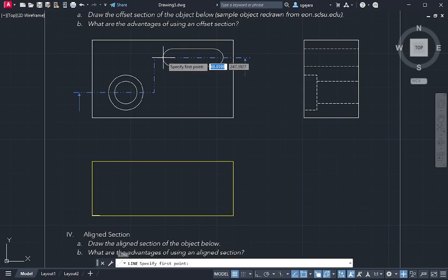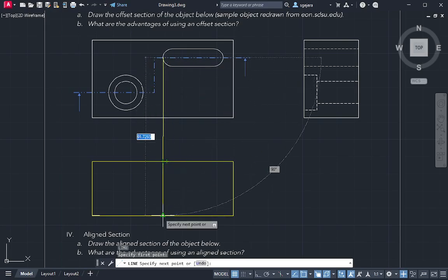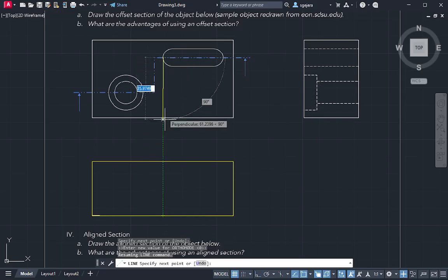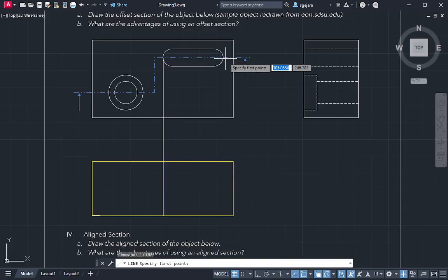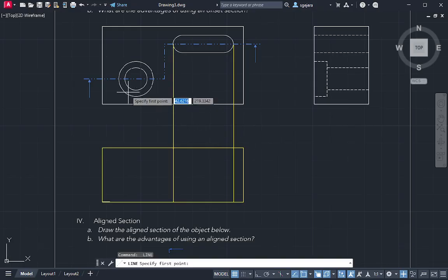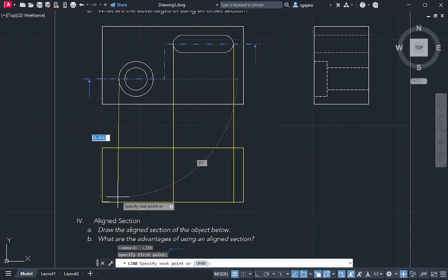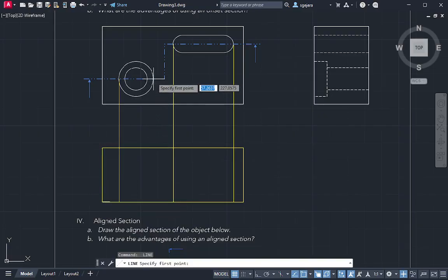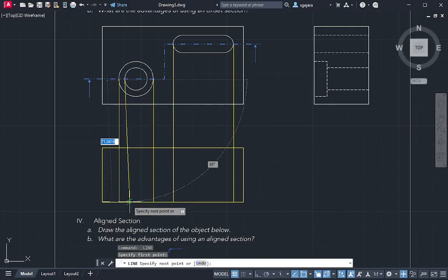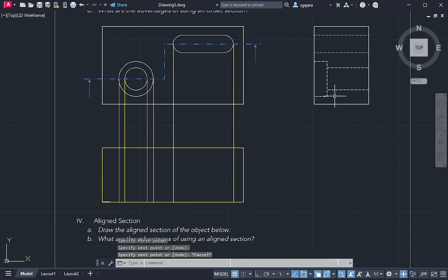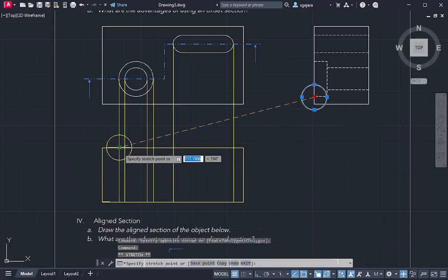Alright, then we'll just follow the profiles. Actually, to make the 2D version easier for this particular example, I'll just bring this down. This also, bring it down, like so. Then this one, I'll also bring down like so. And this one, we'll just copy. Just a projection line going down. Then I'll copy this distance for the basin and place it here.